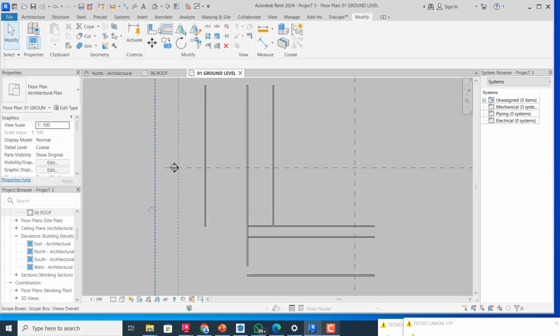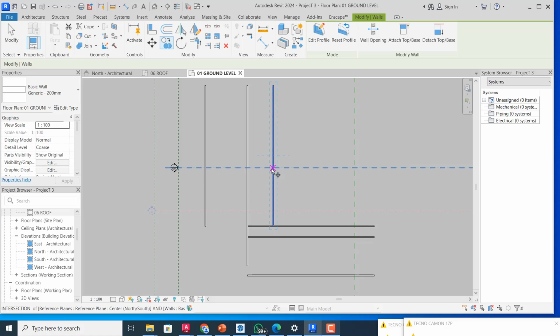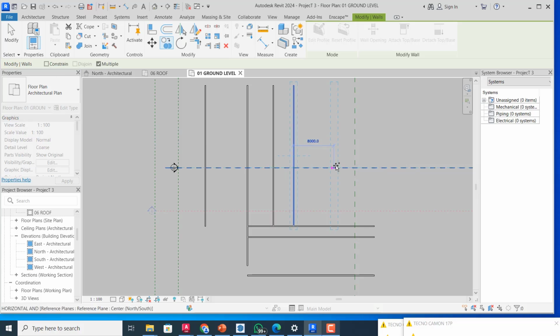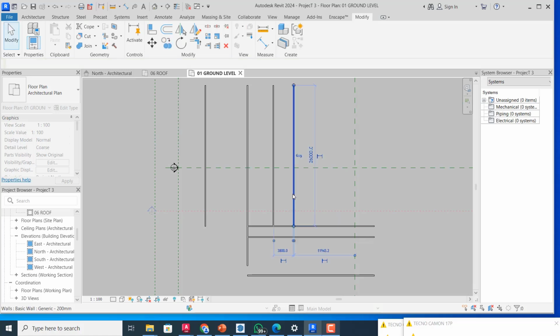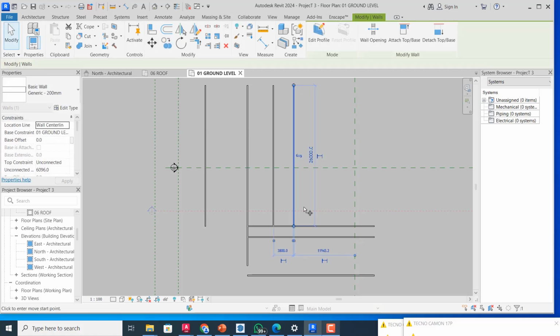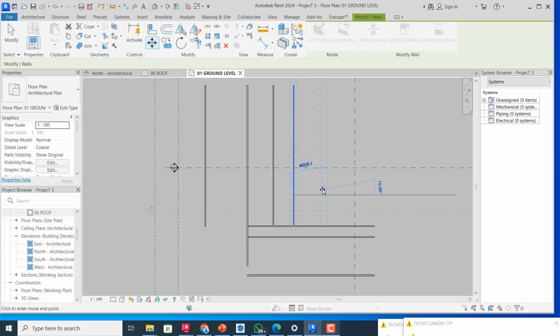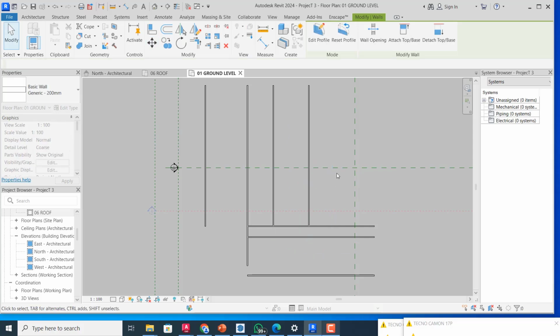We have been able to go through the line, the offset, the mirror, the move tool, and then the copy tool. I have demonstrated that it is similar. Just click on it, click on copy, and then just move your hand along the direction. You can even specify the distance where you want this to be copied. Similarly, like your move as well, you can click on this, click on move, and you can just specify the distance where you want this to be moved to. So let's say this is 3 meters, for example, and it will be moved to 3 meters distance.